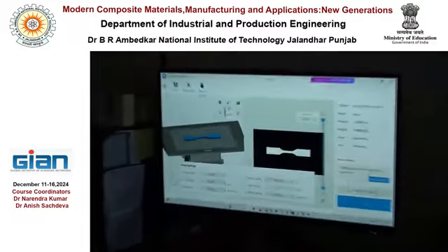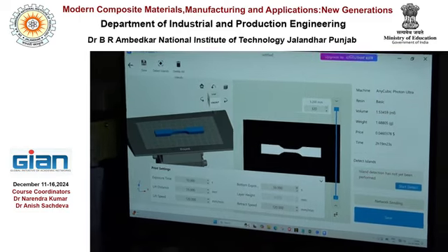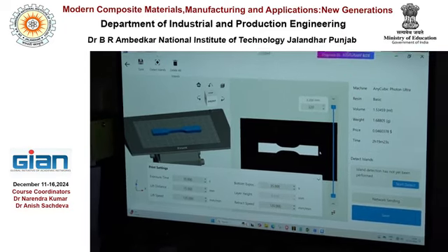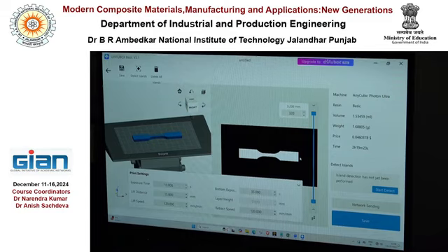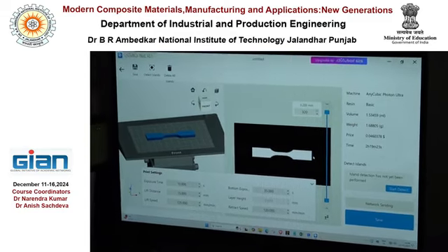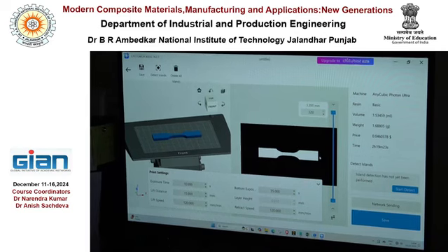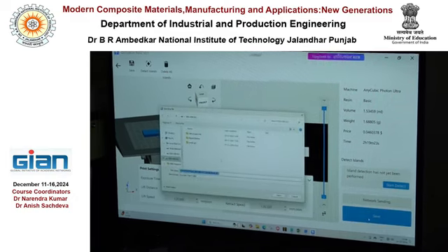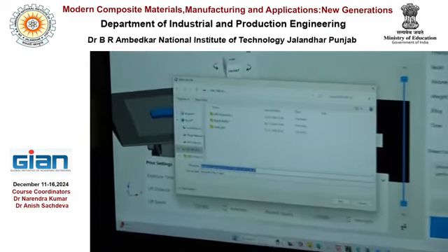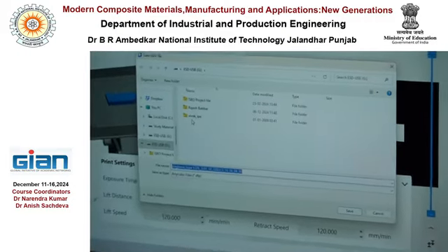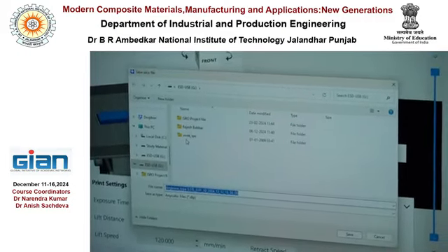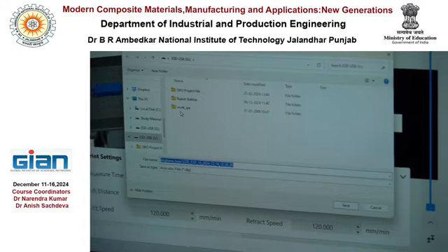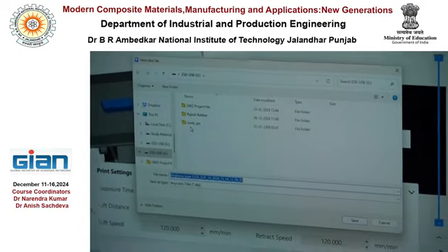If we divide 3.2 mm by 0.01 layers, it will be around 320 layers. 320 layers into 10 seconds will be the overall time of that slicing. If we save it, it will be in the .dlp format. You can save it on any pen drive, similar to the FDM case. We can also load the file on the DLP printer and quickly print your specimen.